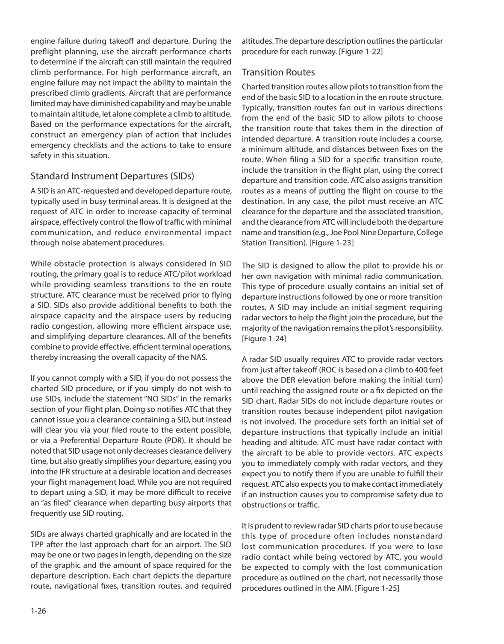ATC clearance must be received prior to flying a SID. SIDs also provide additional benefits to both the airspace capacity and the airspace users by reducing radio congestion, allowing more efficient airspace use, and simplifying departure clearances. All of the benefits combine to provide effective, efficient terminal operations, thereby increasing the overall capacity of the NAS.